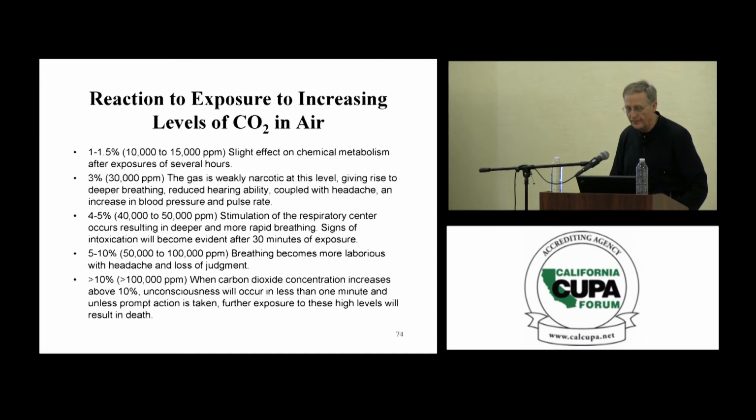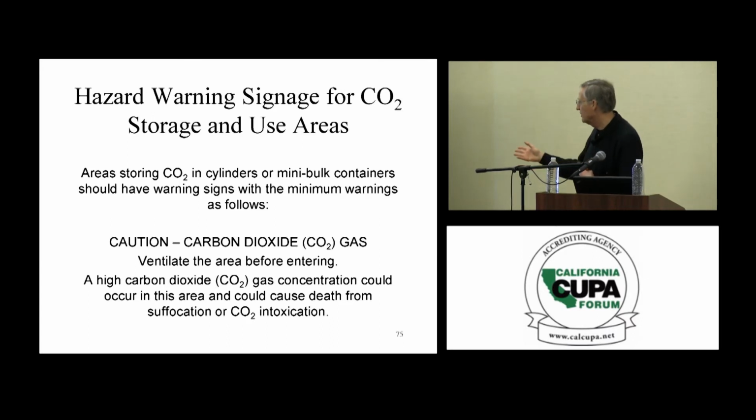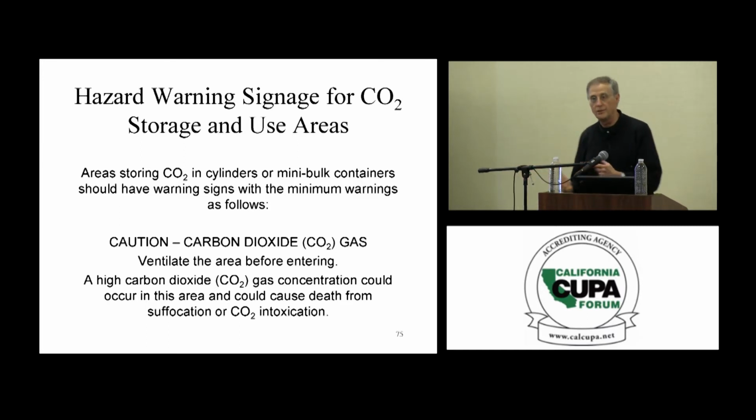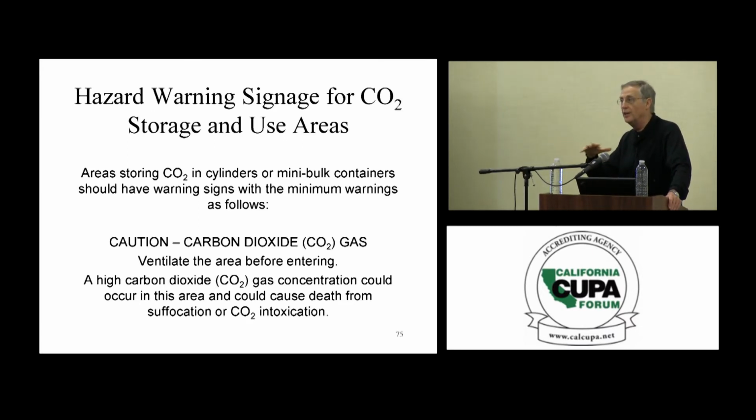And I've put in here that I think this needs to be considered on warning signs, which it typically isn't. It just talks about the asphyxiation hazard. It needs to talk about the CO2 intoxication hazard. One of the reasons CO2 is particularly dangerous in areas where it can accumulate is that it is more dense than air. And so it can accumulate near the ground level in the breathing zone.